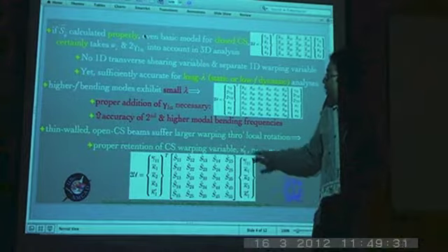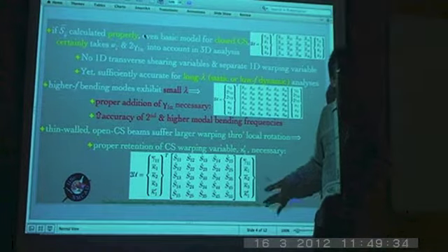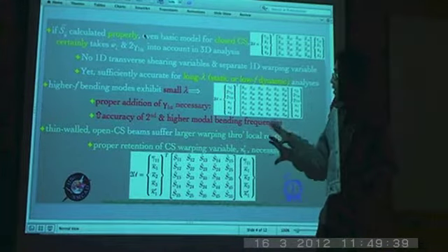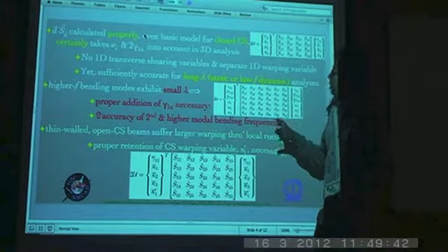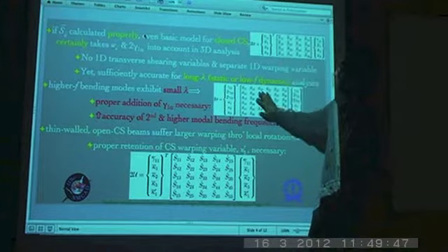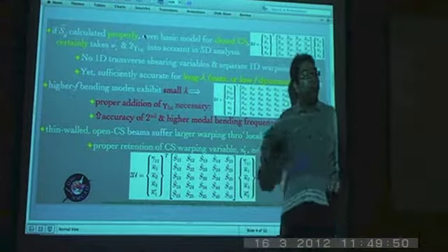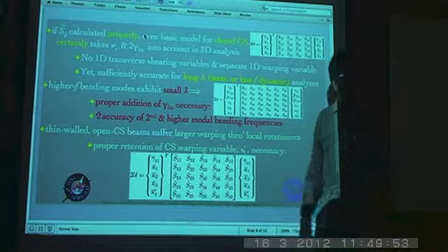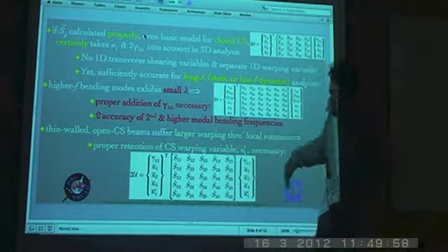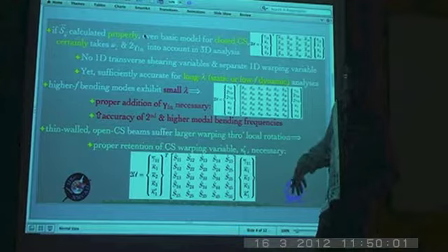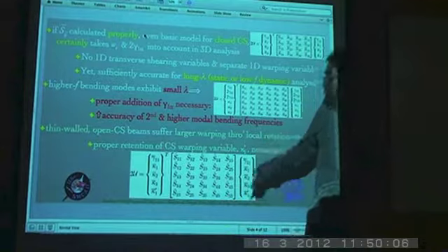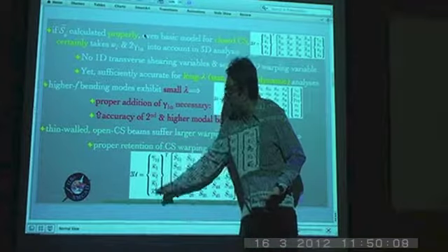So with this, we'll have one more concluding slide regarding the kappa 1 prime, before we venture into non-linearities in the cross section. By this we mean that these coefficients, namely the S bars or S hat, will either be functions of the one-dimensional strains, or you can retain them in a constant form and add some more terms to this, which are basically non-quadratic, which contribute to the non-linearity as far as the dependence of the derivatives of this 1D strain energy is concerned.